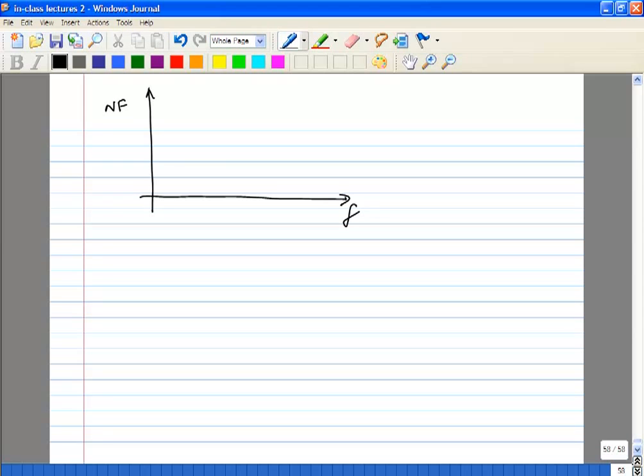It's not 3 dB actually. No, that is only if you are using a resistance at the input, right? For this one, Fmin is actually much smaller. It has some form 1 plus something, a lot of constants times omega over omega t. Remember that? We'll come to it later in today's class also. So it increases with frequency, maybe some kind of nonlinear increase.